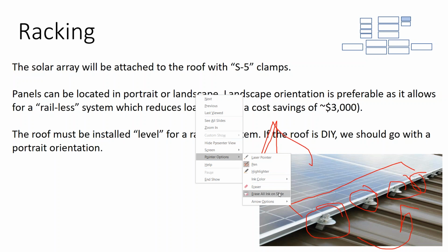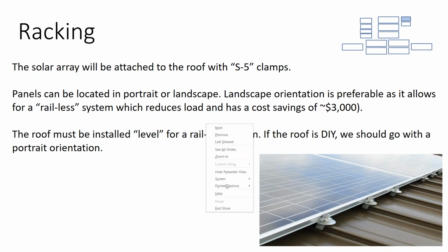And so while I absolutely agree with solar installers who, when they're on an older shingle rooftop, really don't like railless racking systems because of installation and alignment issues, at the end of the day, on a standing seam metal roof, I almost feel like you have to go with a railless system because it's so much better structurally for the rooftop.